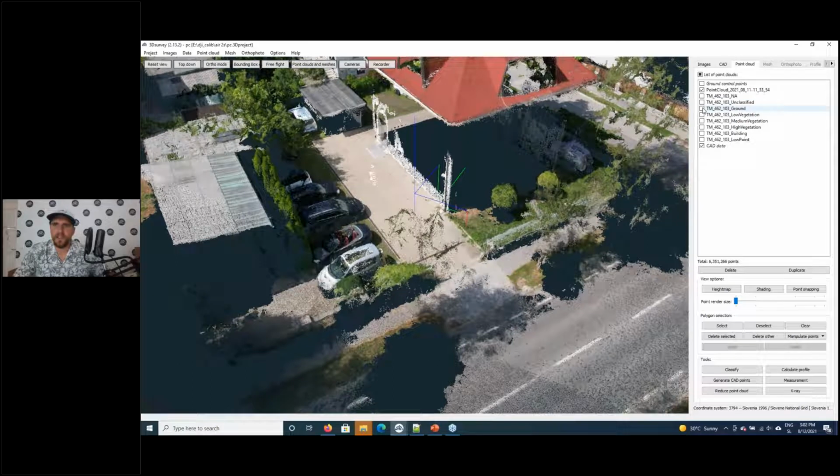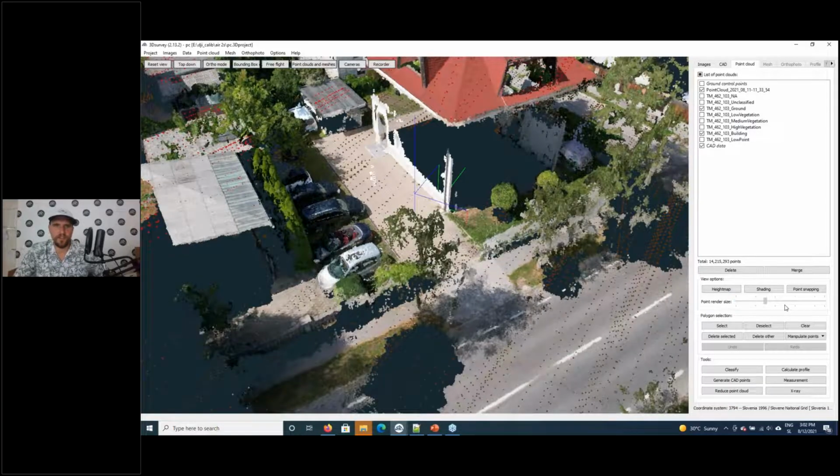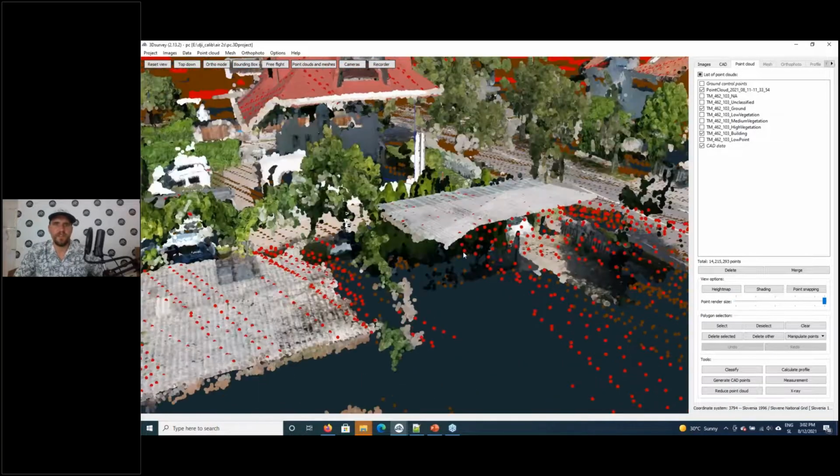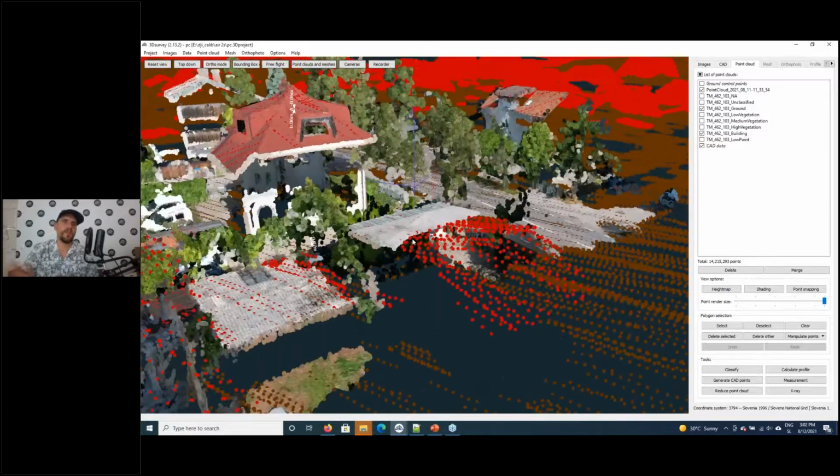Turn on the ground and building layers. Increase the point size so that we can see them. Because the difference is systematic, we know that probably either our GPS or their GPS showed a slightly different value. Also, this LiDAR data is now already maybe 7 years old. Back then, maybe they applied another geoid model, because of course it was updated, and when they update it, it changes by a little bit.